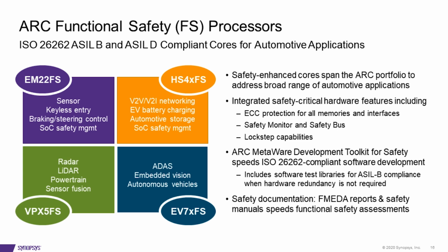Again, all of the safety features are pretty common, and I'll show a slide next that walks through a few of them. But basically, we're trying to make sure that the lockstep capability, ECC protection, and how we go about designing and developing that IP is consistent across the board. We also have compliant tools, so that's an important aspect as well. You simply can't put some hardware out there and say, okay, it's certified and it's going to meet your needs. You have to have a tool chain that's also ISO 26262 compliant, and our MetaWare development toolkit for safety around all of our processors meets those needs.